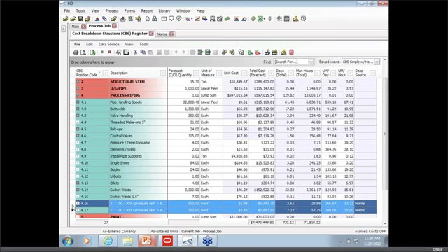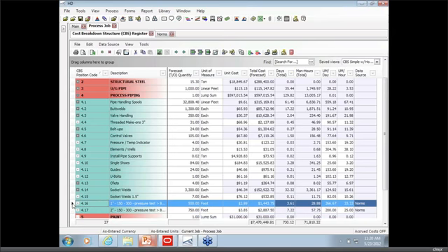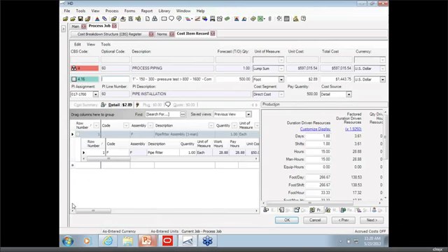And then from there, we can go in and actually inspect the individual record and see how that cost is being driven. So that norms database is leveraging a pipe fitter assembly. It had the productivity measurements already in there. So essentially you're doing 266 feet per day. The total duration with the man-hour factors added onto it is going to be just under 4 days. So the whole point of this is to leverage your historic information, leverage your norms data to help streamline your project, streamline your estimates, and have some standardization as far as the breakdowns.